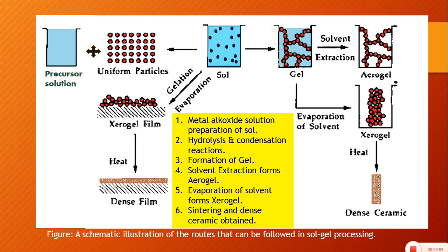That state is called the supercritical. So here there is shrinkage. Although the network is retained the same, there is a shrinkage over here due to extraction of the solvent, and this shrinkage is very low. It is about less than 15%. Okay.